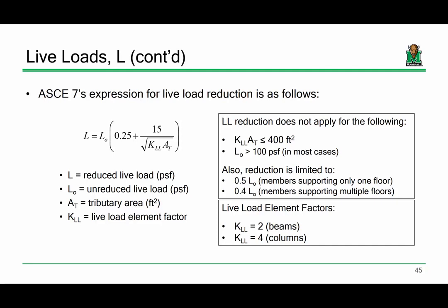But in all seriousness, the library is actually going to see that load. So anytime that your live load is greater than 100 pounds per square foot, you can't apply live load reduction. You have to take the load as is. Okay, so that's another point worth mentioning.